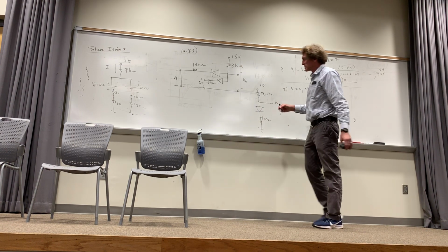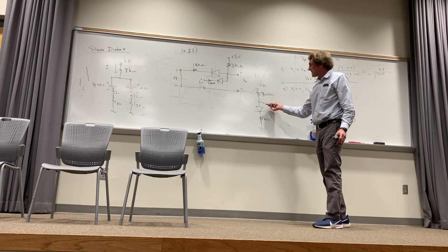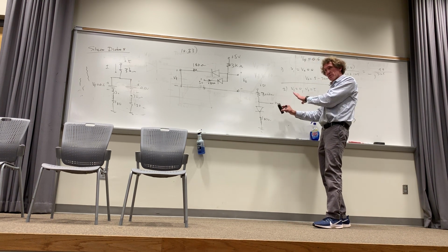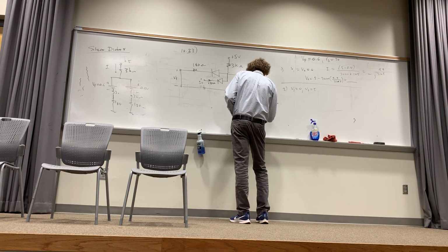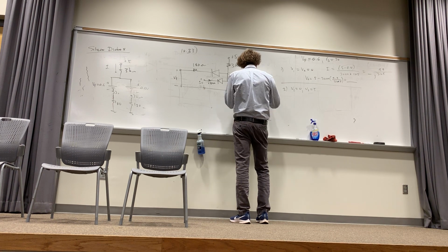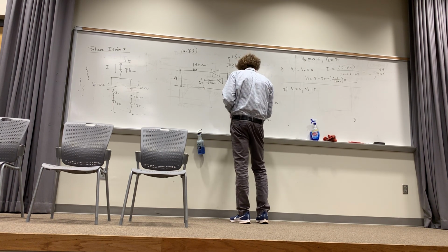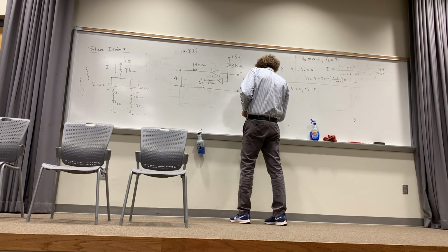Now, the answer is obvious, but can current flow that way? I need to get at least 0.6 volts there, can I? Class? Yes, it's on. If it's on, what does it look like? Replace the diode with a battery that's resisting the current flow, which is going to be the forward voltage, the on voltage, which is 0.6, and the resistance, which is 30 ohms right there.